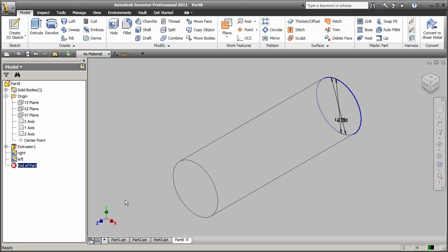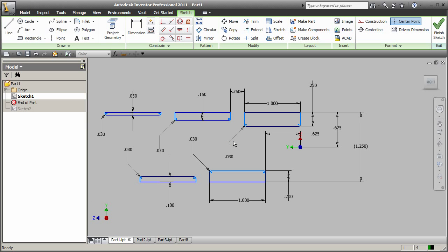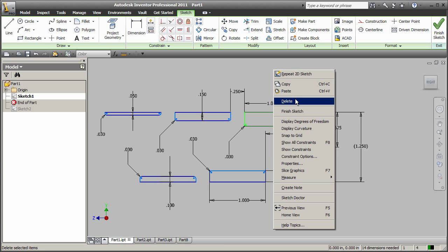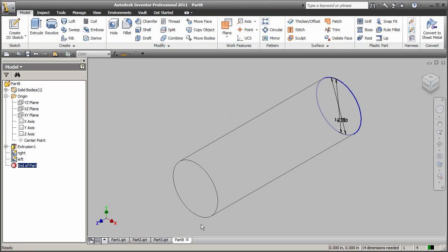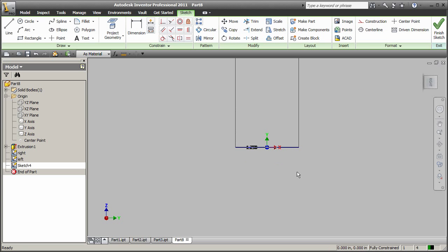So now let's begin working on the flight geometry. Now I've created a basic sketch, and you can see how I have the flight geometry. And what I've done is I've created the transitional depths in each one of these sketches. So we're going from 1/4 inch to 50 thousandths. So let's go ahead and copy this first sketch. Let's go into our YZ plane and paste that geometry.